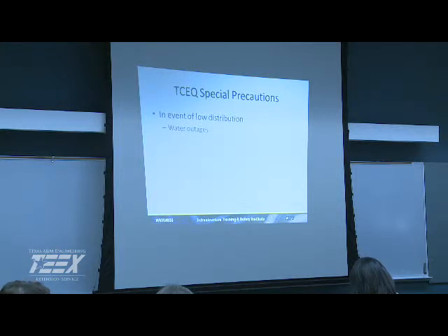When do we have to be careful, or when do we have to pay attention with our sampling? If we have low flow issues, what do y'all require? You have to have less than 20 for a certain period of time. Roughly 20 PSI. Then you got to pull samples. Okay.